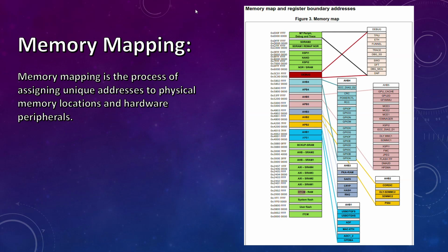First, your program is stored in flash, and when power is applied, the CPU starts reading the instructions from flash. While executing, the CPU uses RAM to store information temporarily. If permanent settings are required, they are stored in EEPROM. And that's how a microcontroller operates internally. CPU works with memory to execute your program.